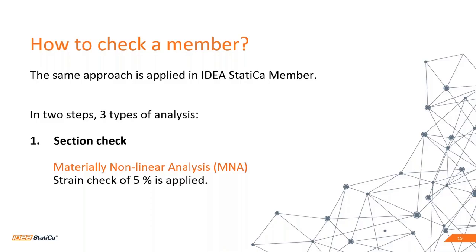It uses the nonlinear material, so we call it materially nonlinear analysis, and we limit the plastic deformation based on the national standard, basically with 5% of plastic strain.